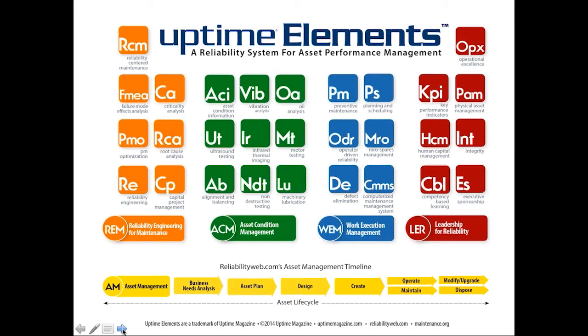The other concepts that come out of the green asset condition management is precision lubrication, always starting with clean, dry, compatible lubricant, and working to a precision standard for alignment and balancing standards of all your rotating equipment, both new equipment and repaired equipment being put back into service, having trained technicians that are given ample time to create precision balanced and precision aligned equipment. We call precision approach defect elimination because it stops the defect from entering into the system, so you shouldn't have to detect it out using these advanced condition monitoring technologies in the future.